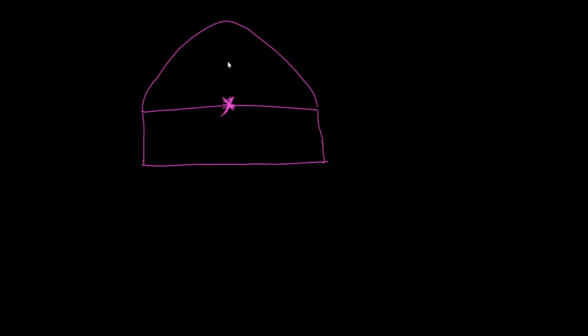What will you do? For the semicircle, you will calculate the area moment of inertia about this one. The centroid formula, you know, how much is this one? We have already discussed this in the centroid chapter: 4r by 3 pi. You will calculate the area moment of inertia of the rectangle about this axis, xx. Then you will calculate the area moment of inertia of the semicircle like this.